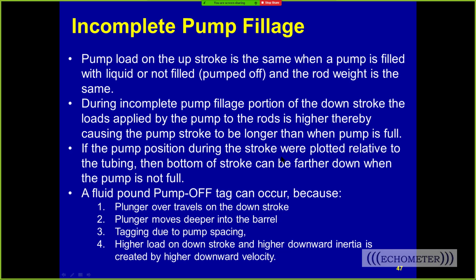So when is a pump not full? Well, on a pump off controller, when it pumps off. I was teaching a class about 5 years ago, and someone in the audience said, "What about pump off strokes?" And I said, "I don't know what a pump off stroke is." And he said, "Well, every time our wells go down and pump off, we get a tag." And I said, "Cool, I've never seen that, but it makes sense. Since the load on the downstroke is being maintained, it's going to cause the plunger to move deeper, and that's going to cause a tag."